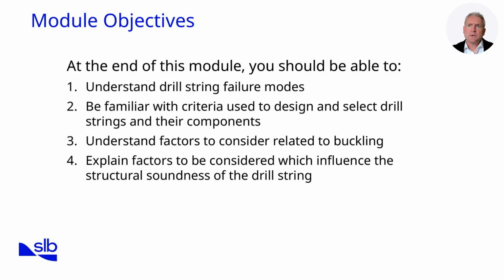We then turn to bottom hole assemblies and how their design controls trajectory. The type of BHA chosen, whether for vertical, build, or hold sections, dictates drilling efficiency and directional control. Alongside this, we examine how weight on bit changes with inclination angle and how indices such as the curvature index CI and stability index SI help optimize performance.